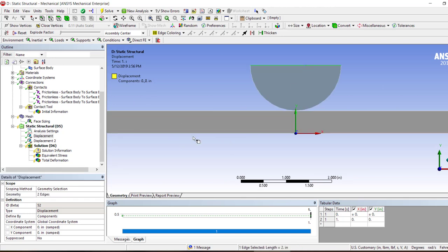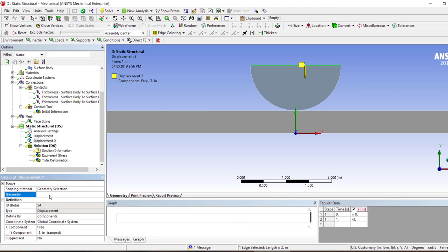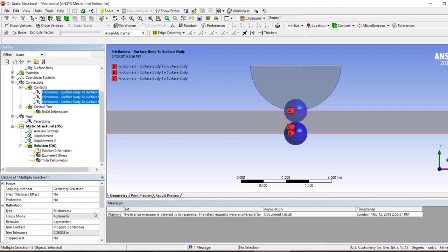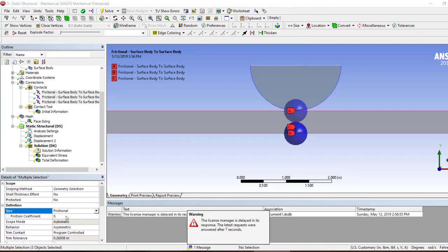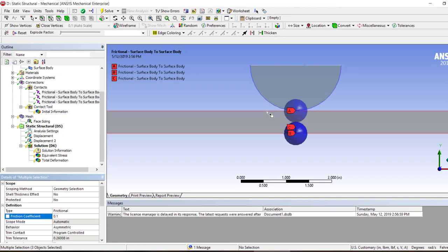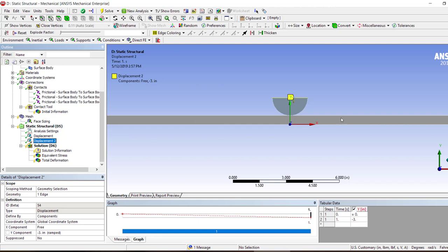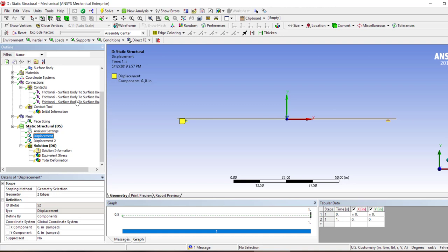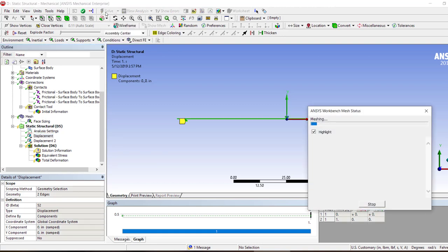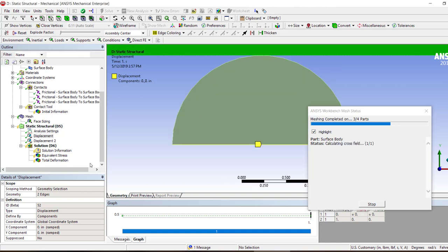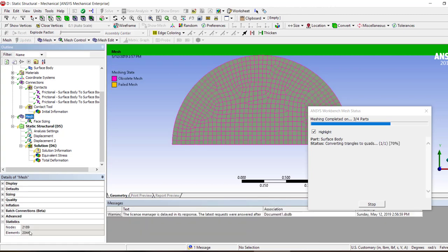And it also could be setting off because we applied it frictionless rather than frictional. So let's also try that. Make it frictional and make it like 0.1, and then we can try it, like run it. So the displacement is -3, and these are fixed in XY, and let's solve it. And now you would see that we would have less elements. So previously we would have, I guess, like 22,000.